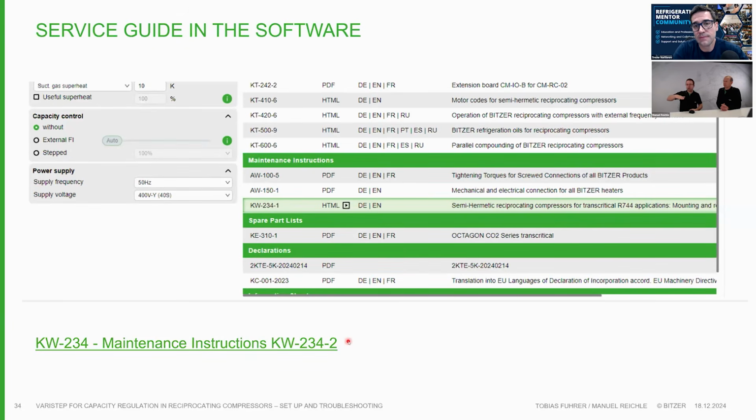Because if this is going, let's say, from 5 volts to 10 volts and it's dancing up and down, jumping, then the controller or the IQ module cannot react perfectly on this, because it also needs a stable signal, and not saying I need 70%, I need 10%, I need 100%. So checking the 0 to 10 volt signal is also an important thing.